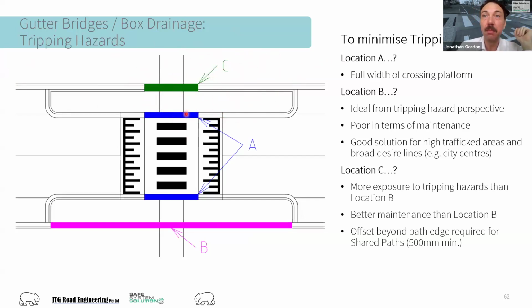And let's say the minimum clearance is 500 millimetres extended from each side. If you recall that diagram, which I haven't listed here, desirable is 1 metre beyond the edge here, so you can consider those additional extensions. For just a wombat crossing such as this, there's no actual requirement to extend it across, but I think it's a little bit unnecessary to not extend it beyond the path edge at all. So I'd suggest a minimum of 500 millimetres is how far you'll be extending these beyond the edge of the path.